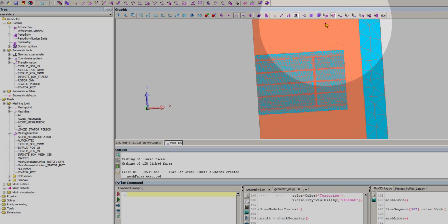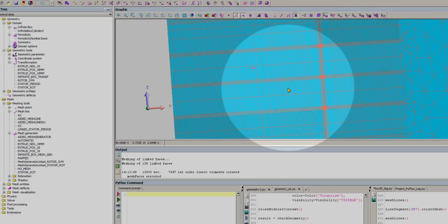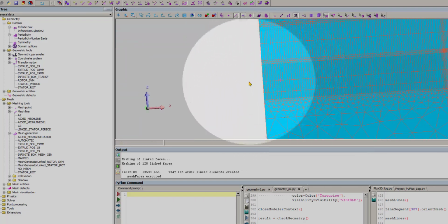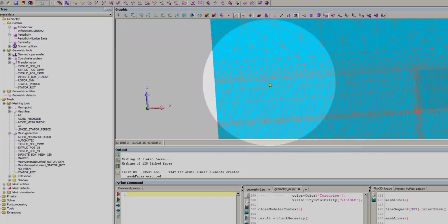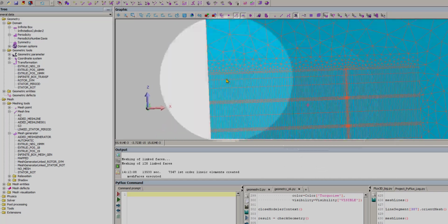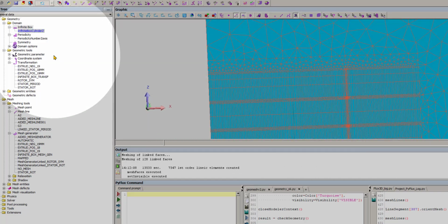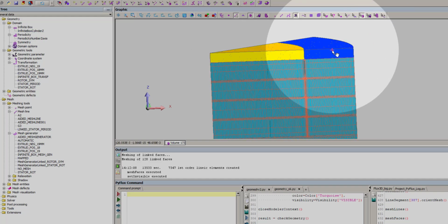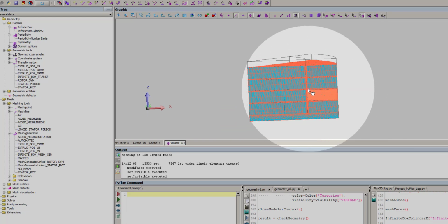And now I can see that the borders are very well meshed, and I can keep two layers inside for the extrusive mesh in the central layer. And as you can see also, the junction between the step skew layers is very well meshed.